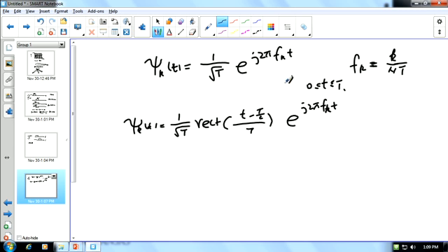Okay, and then you will ask about this term here. Based on the property of the Fourier transform, if you still recall, if we do a frequency shift, if we shift the signal to a different frequency, then we need to multiply it by e^(j2π f_k t). Okay? Any question? So if you look at its spectrum, that's how it looks, a sinc function.